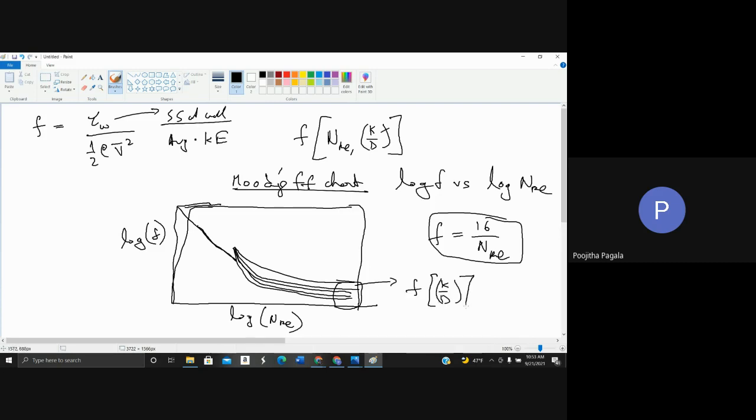That is, it is no longer dependent on the Reynolds number. And higher the roughness, higher is going to be the friction factor. So any questions about the Moody's friction factor chart? Is the interpretation of the chart okay? Okay.